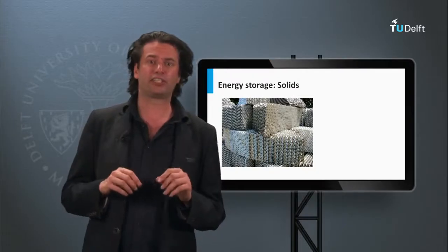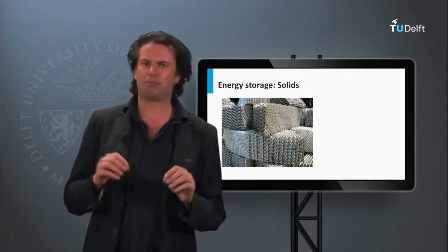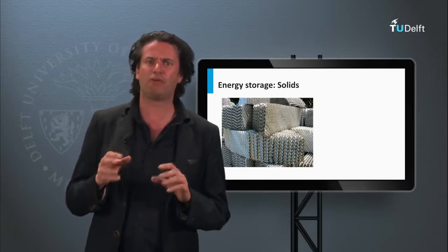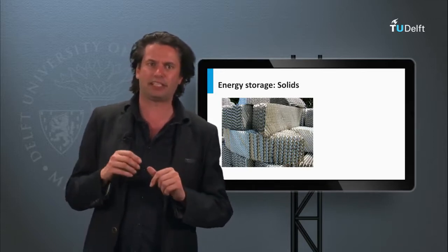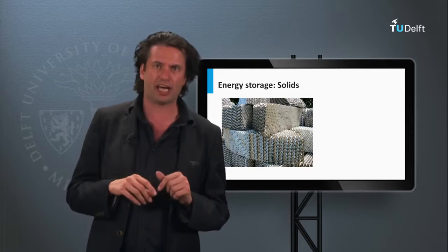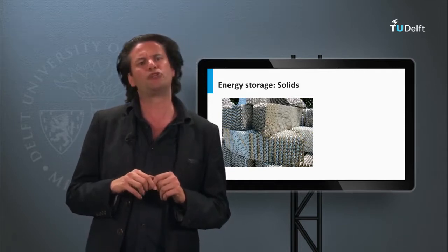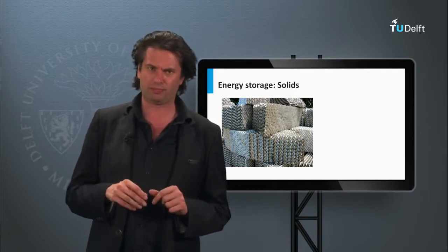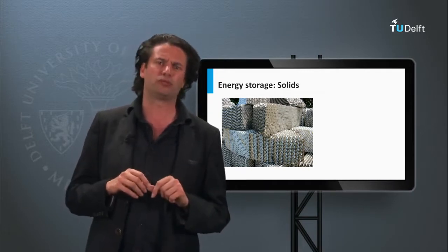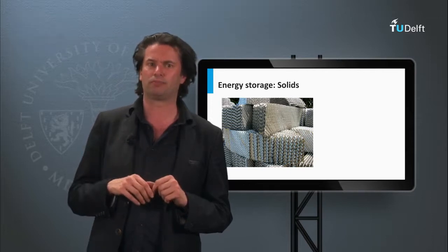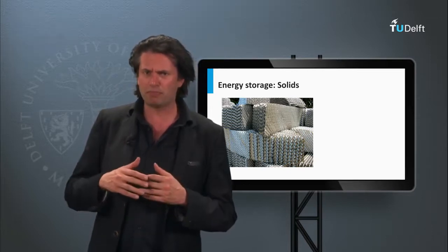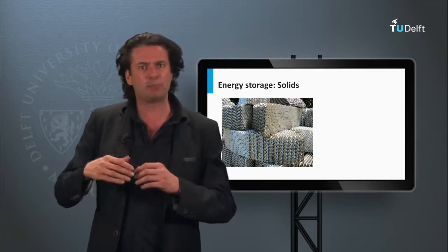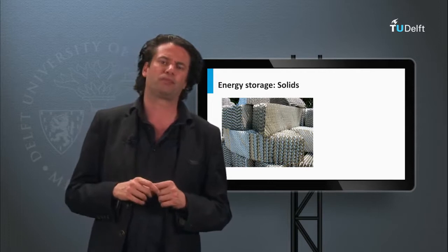Another type of energy storage is the so-called packed bed. It's based on heat storage in solids. It uses the heat capacity of a bed of loosely packed particulate material to store energy. A fluid, usually air, is circulated through the bed to add or remove energy. A variety of solids can be used, rock being the most widely used. In operation, flow is maintained through the bed in one direction during addition of heat and in the opposite direction during removal.